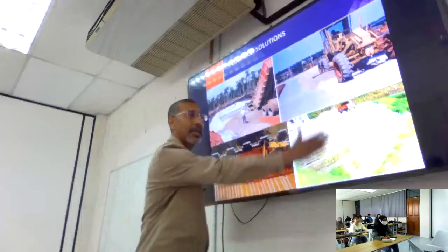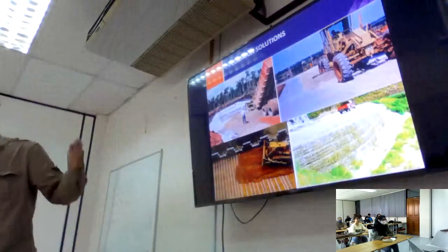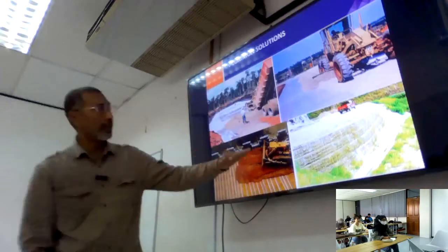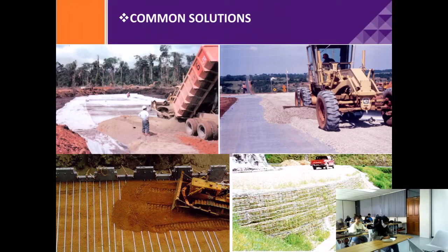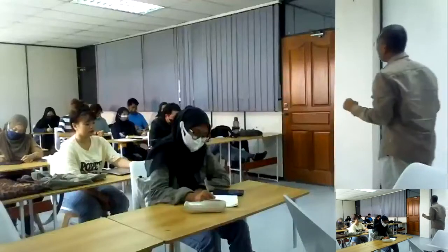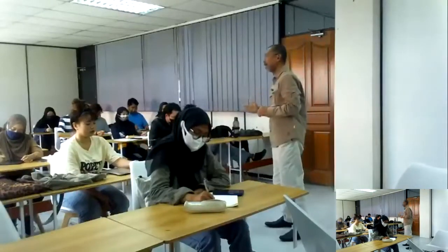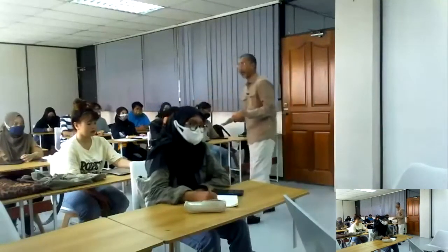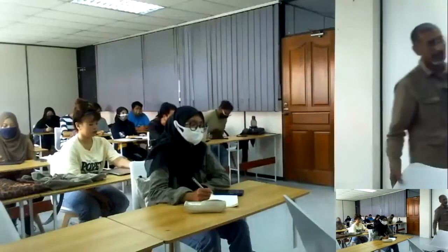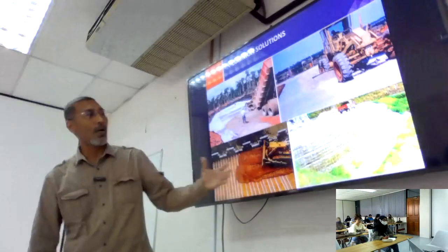You create this vertical wall by wrapping the soil little by little, at every 300 mm thickness, and then you start going up, stacking it up, and that will create a composite, you can say a bag, that covers a big area of space to create this almost vertical wall.